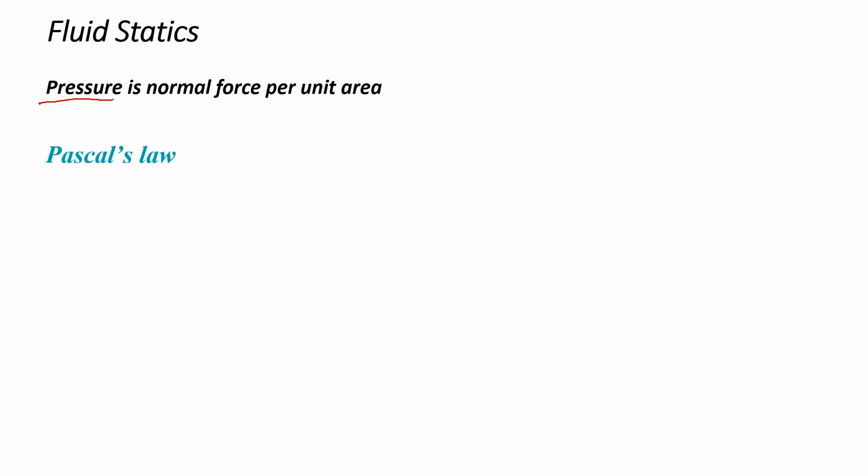Then we started our fluid statics portion, and in fluid statics what we assumed is that our fluid will be at rest. So what are the possible scenarios and the possible equations that we will have to develop to analyze a fluid at rest? First of all, we came up with the concept of pressure, and pressure, as you already know, is the normal force per unit area. And then we came up with Pascal's law, and Pascal's law deals with the pressure at a point.